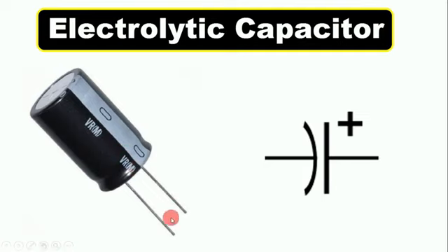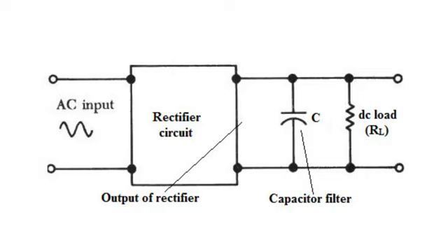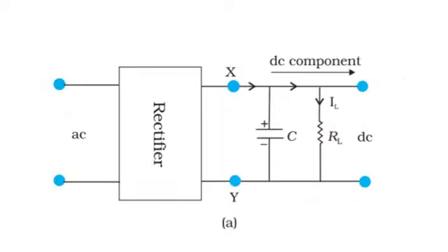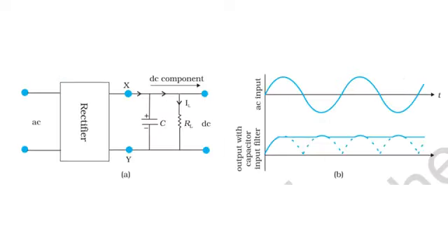If in this capacitor both the legs are equal, then in this condition you have to observe this strip. This gray strip you can see here, on this strip a negative sign is there. This means that this leg here is negative and the other one is positive. Now let us talk about the use of this capacitor. We use capacitors like filters. That is, in our circuit, if there are some noises, to reduce these noises, we use a capacitor.